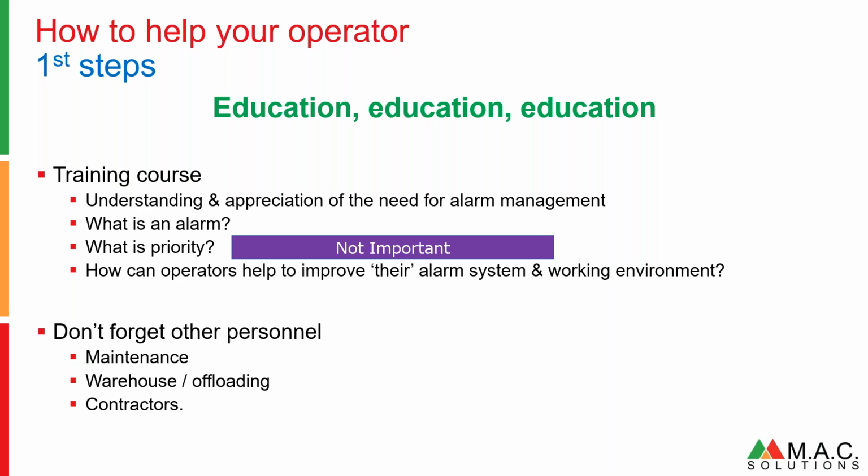And contractors. Many companies will use third-party contractors, third-party configurers to actually write the software, modify the software. Do these guys that you bring in understand alarm management? Do they just proliferate alarms because it doesn't matter? I've given you extra alarms. I'm sitting in a house a couple of hundred miles away from the plant. If it blows up, it's not my fault. Do they actually understand what they're doing?